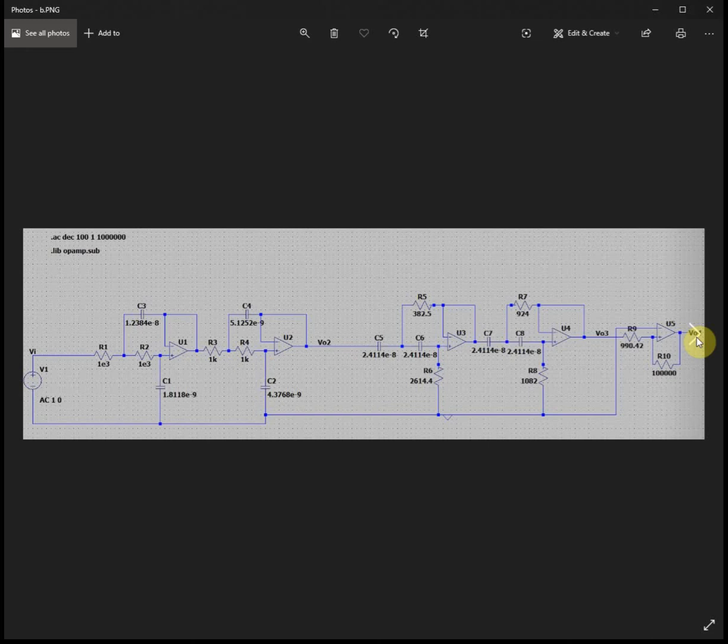This is because we were tasked in the exam to create the gain to have a positive 100. If we were to put it on the negative input of the op amp, it would become negative 100. The values of the resistors are a little bit obscure, but this was because we tuned the circuit in order to have as close to 100 times voltage gain as possible.